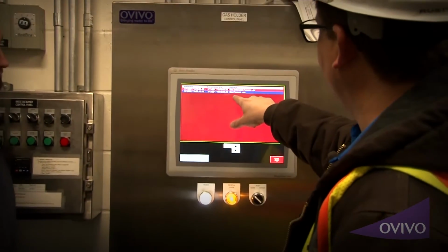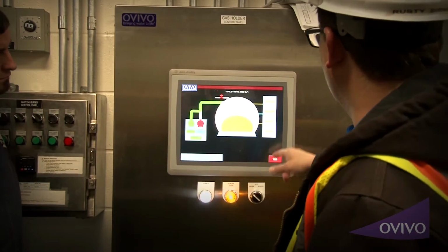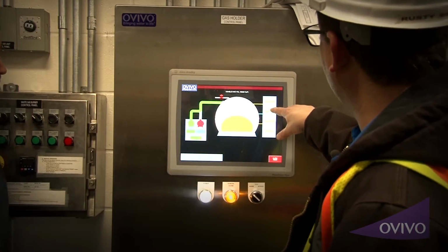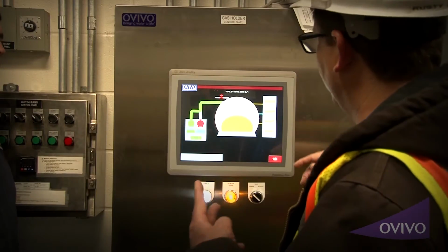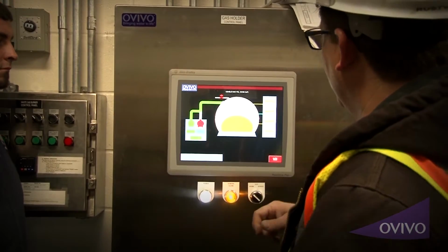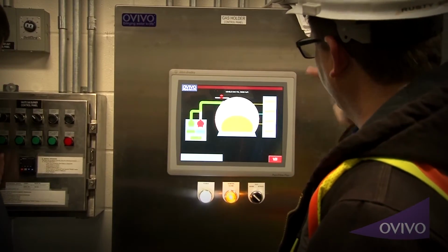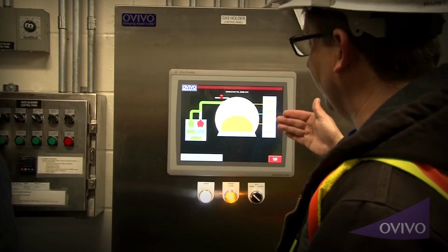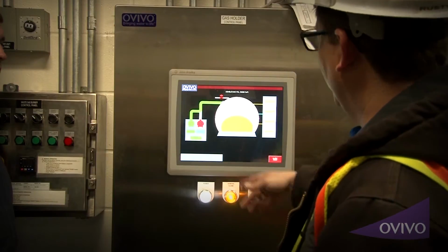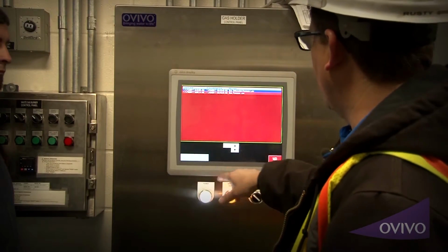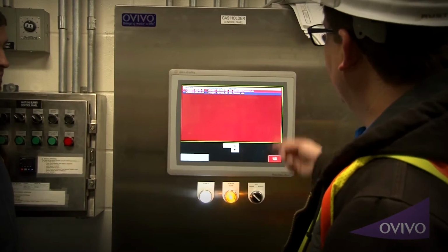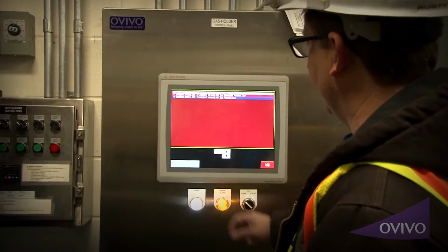But the low gas pressure alarm is because we have shut it off up there at the actual meter itself. So because this one here is not matching close enough to this one right here, it set 2 alarms right off the bat. One was low pressure and one was the differential pressure. And all of these alarms will have to be reset after they go off. So no matter what, if something were to happen and something were to trip and it'd send an alarm, you would have to come back out here, go into your acknowledge the alarm, each one per, and then hit reset. These alarms are not going to go away until we actually get that thing set.